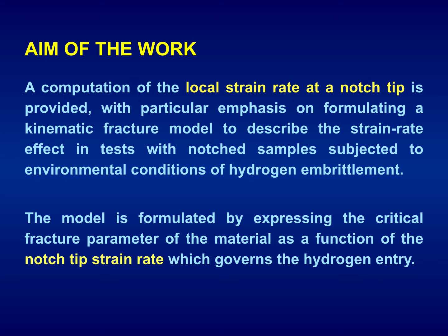The model is formulated by expressing the critical fracture parameter of the material as a universal function of the notch tip strain rate, a one-to-one relationship between this material resistance and the notch tip strain rate, a geometry independent universal curve that governs the hydrogen entry.